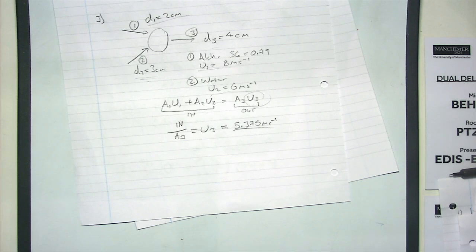So anything coming in is pushing something out the other end. So we only actually need to consider the small slices. And those small slices don't factor in. Yeah, but volumetric flow rate usually equals velocity times area. You're thinking of mass flow rate, I think. Mass flow rate is rho AU, which is what we're going to use next.